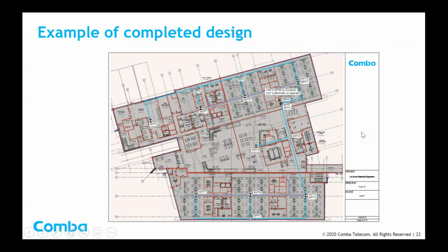Remember I mentioned you'll probably need to update the design. Once he's done the design and then you do the site walk, you might find, for example, oh my gosh, we can't run the coax here like we thought. There is some kind of a wall here that prevents it. So that means this hunk of coax actually has to go here, down here, around here, and back. Again, remember that coax adds loss. So now the designer is going to have to do some recalculation and then end up modifying because of what you discovered on the pre-construction site walk.